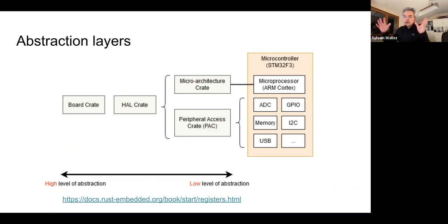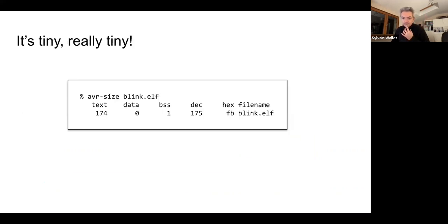And on top of that, it is assembled to compose what's called the microcontroller hardware abstraction layer crate. You have the registers on one side, you have the peripherals on the other side, and with that you have everything to start working. And on top of that, again, we will see that later, there is a whole ecosystem of device drivers. We will see later a small display. That display talks I2C, and it doesn't care about the implementation of I2C. So the hardware layer gives us this abstraction.